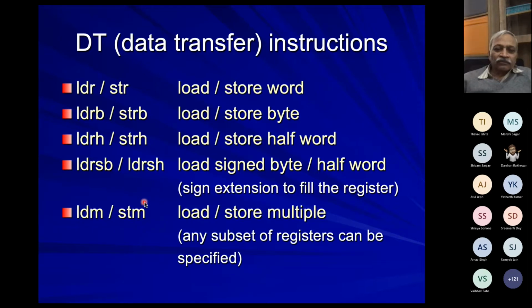But if you want to look at that as a signed integer, then you do sign extension. So here is the pair of instructions which perform loading and storing of multiple registers. LDM STM stands for load multiple, store multiple. Any subset of registers can be specified here, either for loading or storing. We'll not go into details of how you do that. We'll see later. But right now, just note that such an instruction is available.